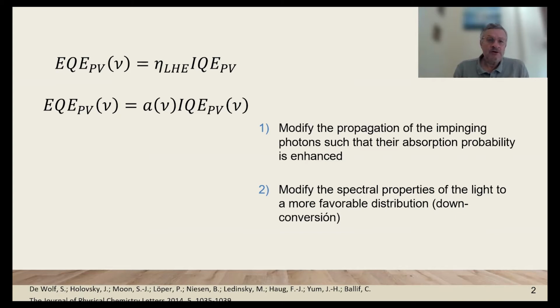The internal quantum efficiency indicates for the photogenerated carriers if they are going to be collected at the contact by diffusion or other mechanism, and the light harvesting efficiency basically is the absorptance. So, how many photons are absorbed from those arriving to the surface of the solar cell.